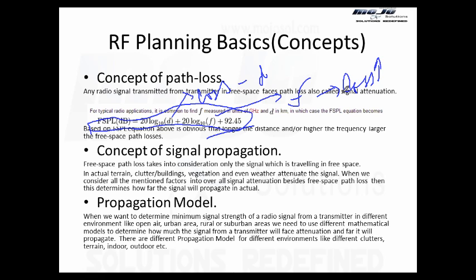And not only will you find these planning tools are very popular, you will see that they have different propagation models. There are companies whose job is to make a more accurate propagation model and sell it to the operators, and the operators run those propagation models, test them, and see how accurately they predict the signal level in their different environments, and how to use them.